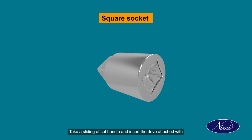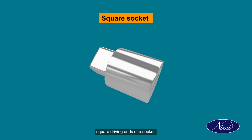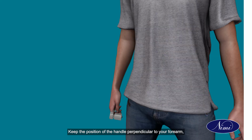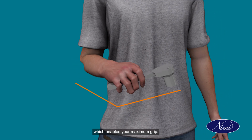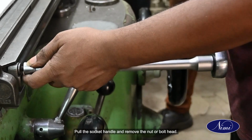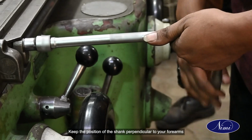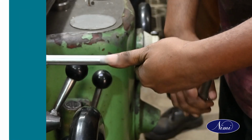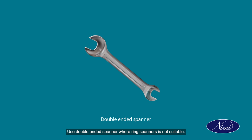Take a sliding offset handle and insert the drive attached with square driving ends of a socket. Insert the socket wrench on the bolt and confirm it is inserted completely. Keep the position of the handle perpendicular to your forearm, which enables your maximum grip. Pull the socket handle and remove the nut or bolt head. Keep the position of the shank perpendicular to your forearms, which enables your maximum grip. Use a double-ended spanner where a ring spanner is not suitable.